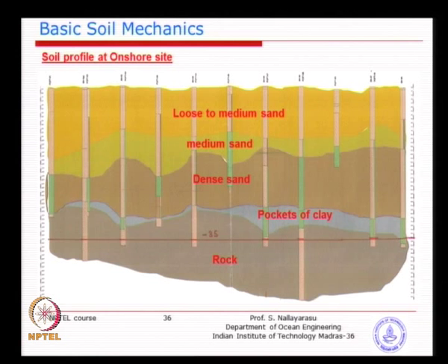The soil investigation reveals that there is a pocket of clay, varying in nature, spread over all the area, and the top 3 layers of sand over a period of time. You can see here dense sand, medium dense sand, and then beach sand, loose sand. So, deposition keeps happening, and that is the characteristic of sedimentary material near the coastlines. So, you can see there.